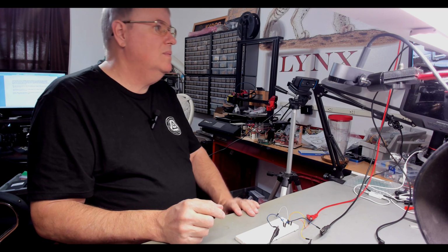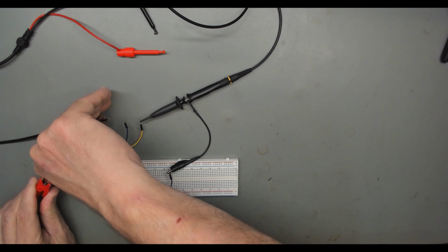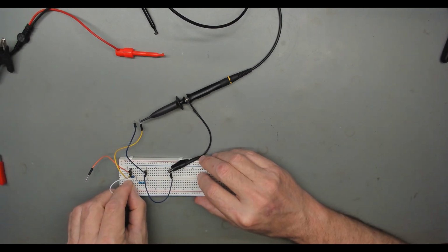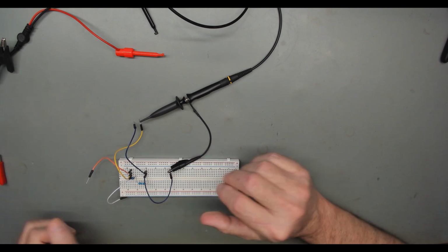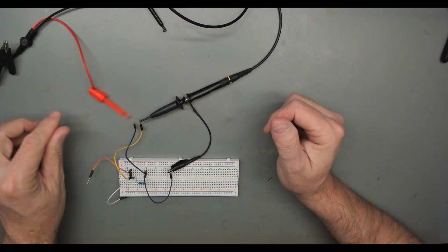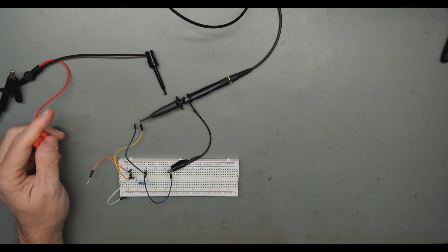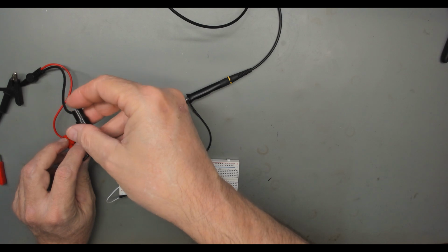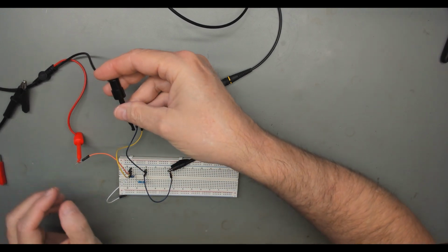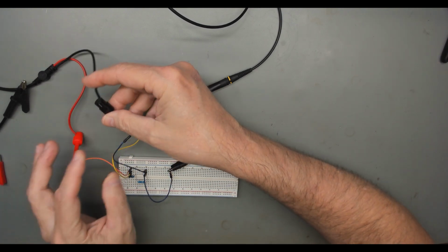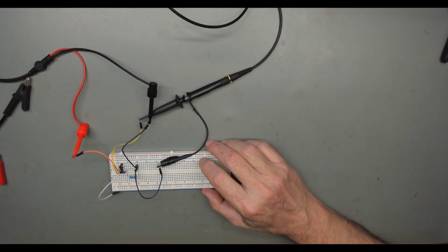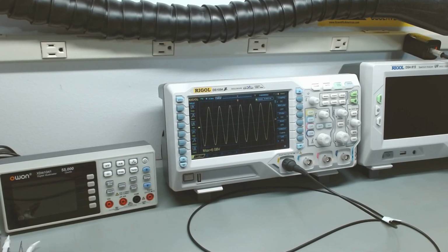Well, that's easy enough. Let me disconnect my DC power supply just to be sure. This is going to short the capacitor out. Let's make sure we short and there's nothing there, okay? And now let's take an input from my signal generator. I've got a 60 hertz 20 dBm signal that I'm going to put into the same circuit. Now we're back on the input. We're looking at the input of the capacitor. So let me turn on that signal, and lo and behold, we see a 60 hertz 6 volt signal coming in.